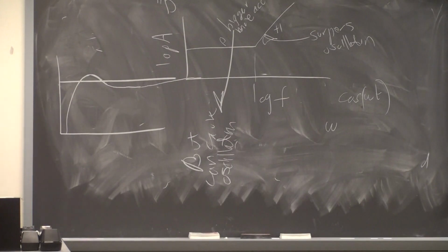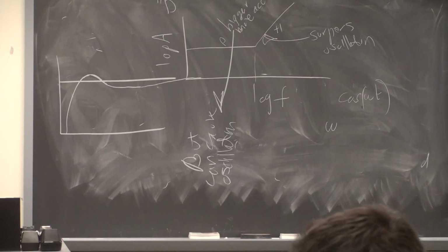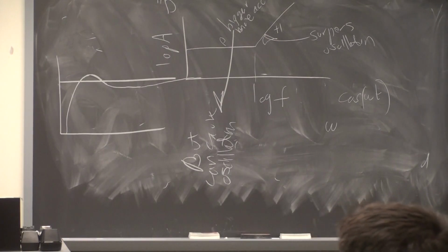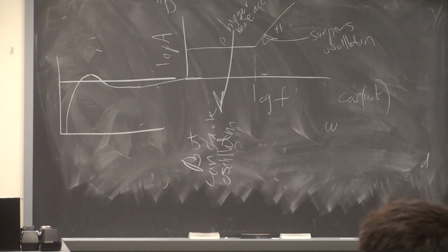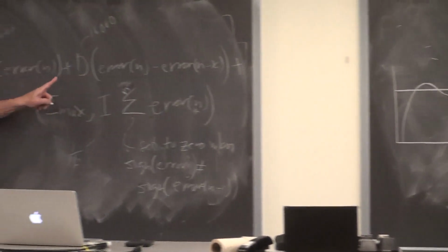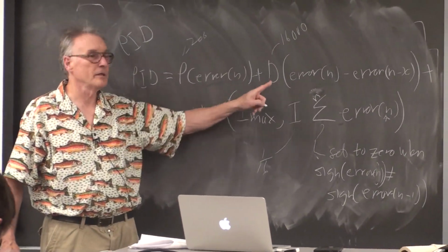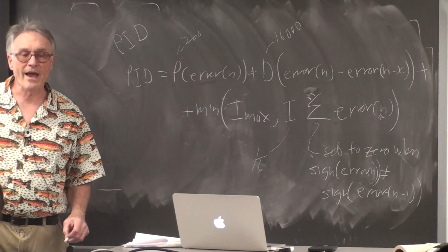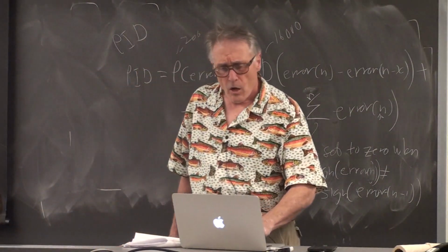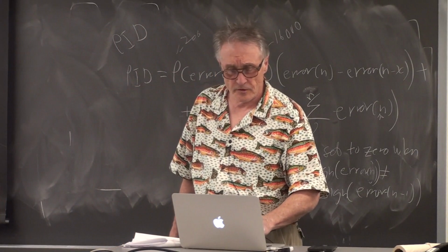So how would you tune this? Set all of them to 0. Turn up the proportional until it starts to fly. Turn it up a little more. And you will find that as soon as you apply the power, the thing tries to go around, around, around. In other words, it's not compensated correctly. So as soon as you start to get unstable behavior, then you add a little bit of D. And you creep up on this by increasing P and D until you get a fast, stable response. Which is why it took me a week to do this, first time.